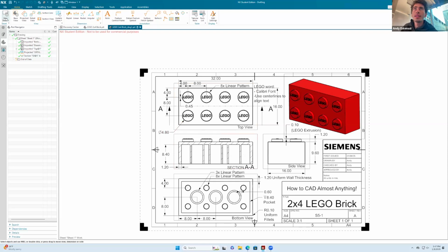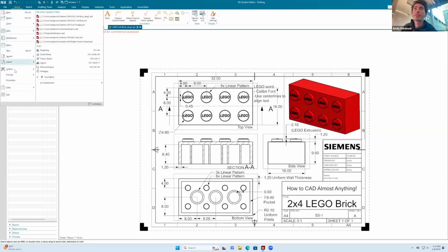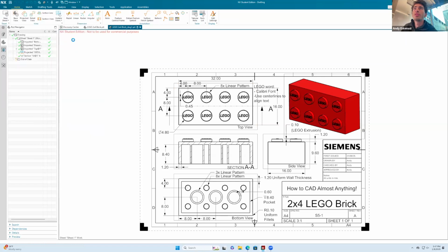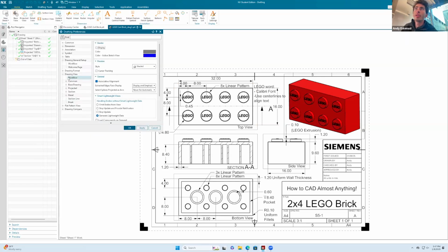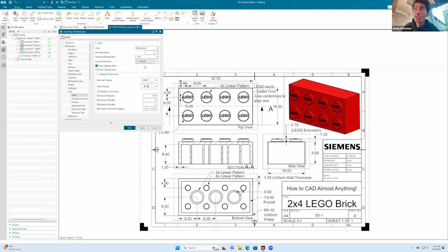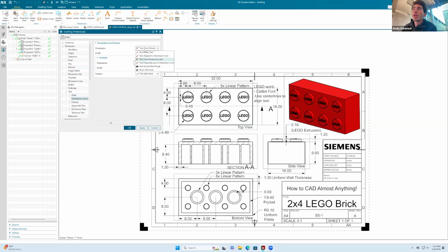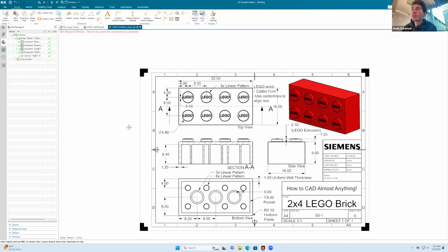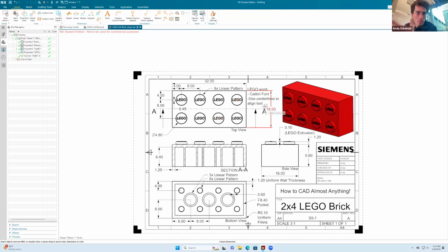I'm gonna go back here to File, Preferences, Drafting. So remember it's here where it says workflow. Otherwise, I believe it's in dimensions, and where it says text, units, I could have systematically changed right here how everything is going to be displayed. And in orientation, I will probably do the same thing. Not many things will change because I had already done it myself, but to show that that's powerful, it's something that you can do to save more time afterwards.